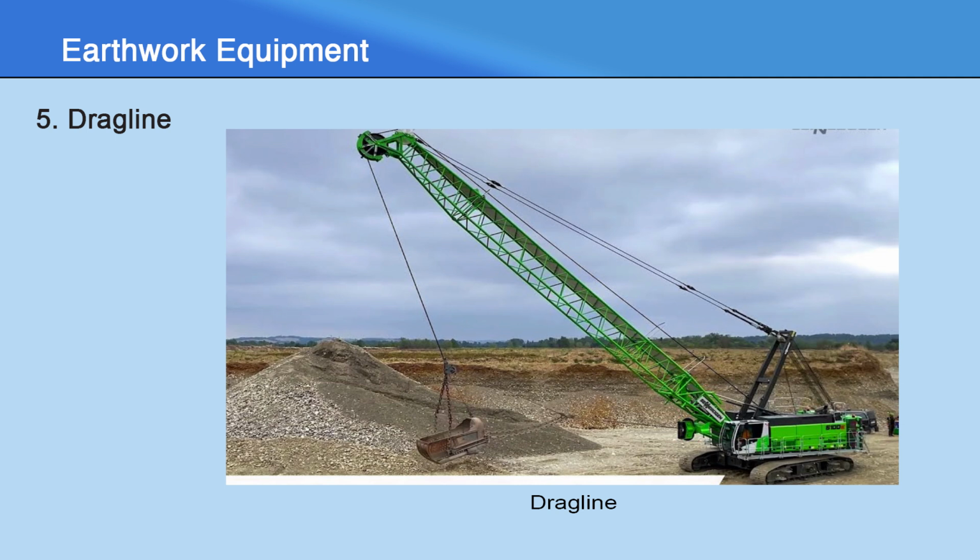Draglines with long booms are advantageous for depositing earth on the banks of dams, eliminating the need for hauling units. It is primarily used for excavating canals and depositing materials on embankments without the need for hauling units. And large-scale earth-moving projects usually employ the maximum utilization of such draglines.